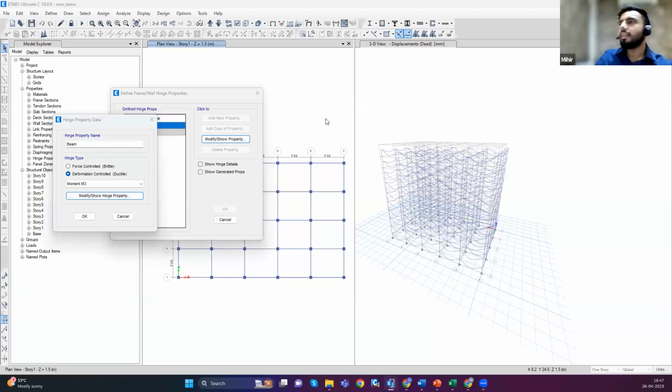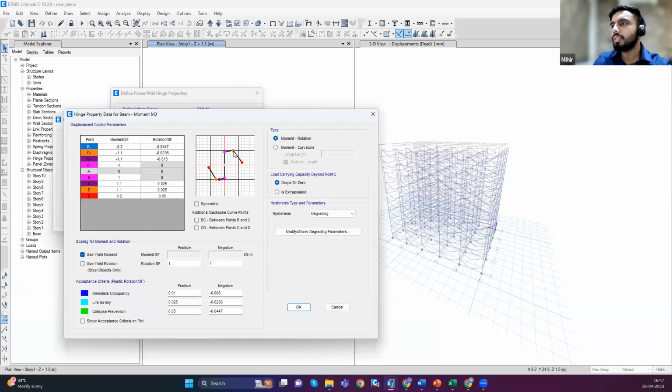So you see, initially we had the curve which was drastically falling from here. That will give you the more brittle nature. But when we are adding this, I would say the ductile behavior, like how the yielding is and post-yielding the plasticity is occurring in my moment curvature. That actually gets reflected in the pushover curve as well. So that thing is important to define the backbone curve when you want to have the ductile behavior.